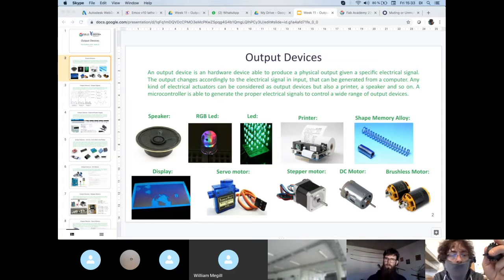The problem is that they will not have a lot of torque at lower speed. I'm talking about these big ones for the machines. So these big servo motors are used when you need a lot of speed and a lot of power at high speed. And this is the case, for example, of the X-axis of our Epilog Fusion laser cutter.